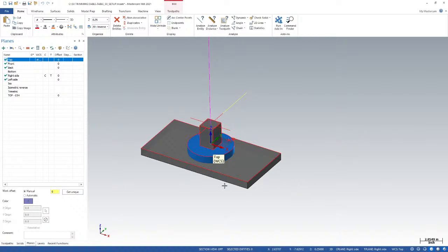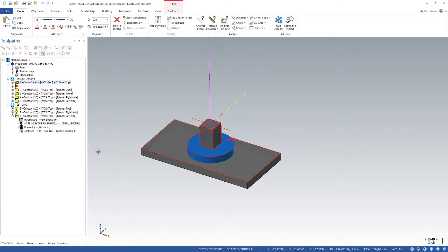When we start to get into 5-axis machining, there's kind of this distinction that's made between 3+2 operations and full 5-axis operations. Now the difference between them is that with a 3+2 toolpath, what we're doing is either rotating the tool or rotating the part to a specific angular orientation, and then typically we're locking the rotary axis.